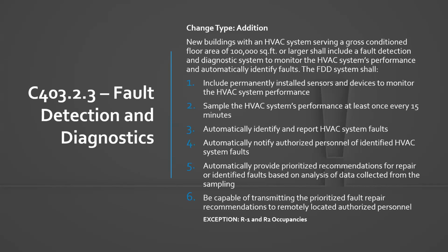Same thing with HVAC systems, though: even though they're installed, you need to see evidence that they were commissioned and are running properly. Are they connected properly? Are they reporting properly? And will it handle the faults as needed? And who will be the person that's actually being remotely notified of any fault detections that are happening? So there's more that goes into that than just whether they have these systems. It falls into the category of, if it's commissioned properly, does it handle all of these 6 criteria that are listed for the fault detection and diagnostic systems.